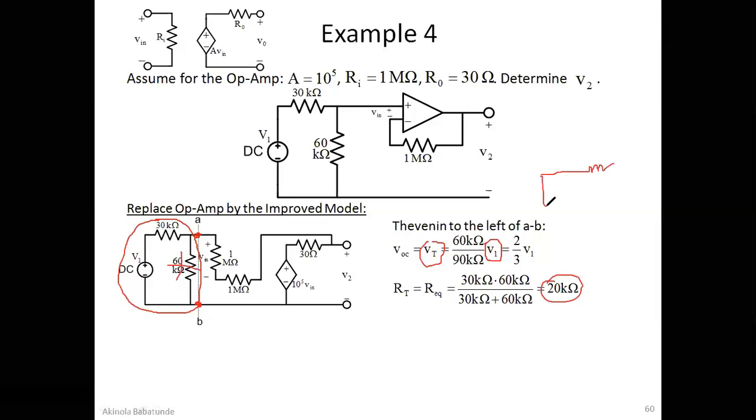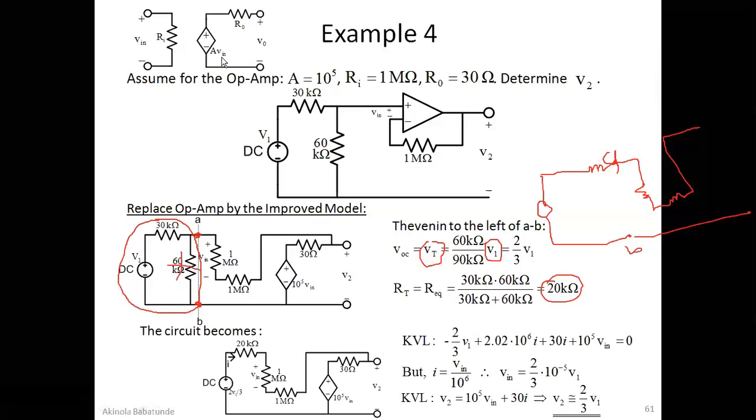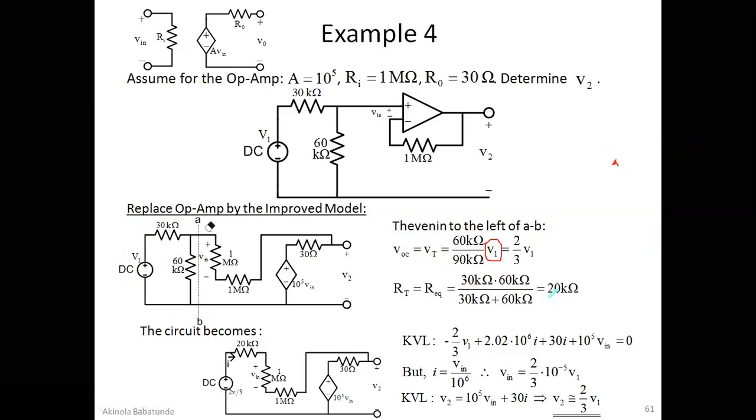Then you still have a voltage source here, and this time around there is no longer any resistance here. You just have a terminal here, and then a terminal here, and then you have your V in, and you continue to the rest of the circuit, and then this goes this way. So this becomes your A, this becomes your B. That's exactly how to deal with these. So we have been able to take out this 60 ohms.